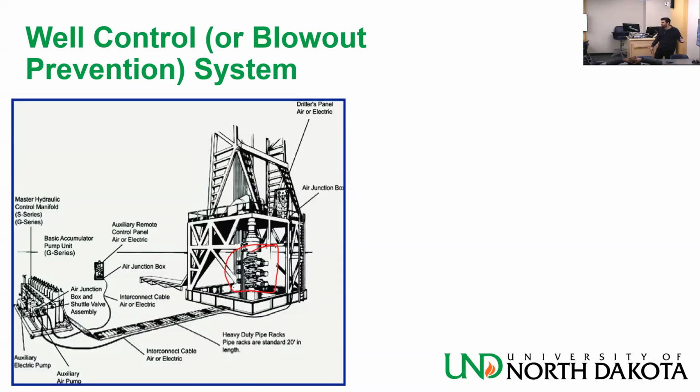Now the pressure on the rams is basically coming from high pressure nitrogen. They usually have the bottles of nitrogen away from the well, so you can access them if the well is on fire, if the rig is on fire. So it's a little bit far away, and they are connected. And there is also another remote control panel really further away that you can access in case everything is on fire in the vicinity of the well. There, basically, it should be the last man standing. The whole rig can melt down. The blowout preventers are the last ones to go.